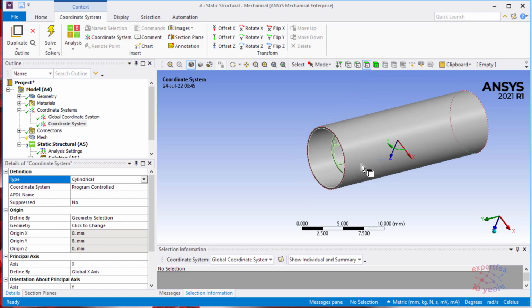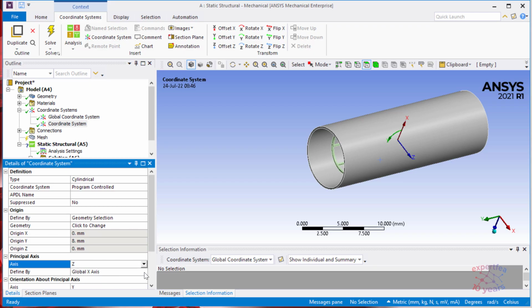The easiest way is to assign the Z-axis aligning to Y absolute axis. So let's go here from the relative Z-axis and align it to global Y-axis.